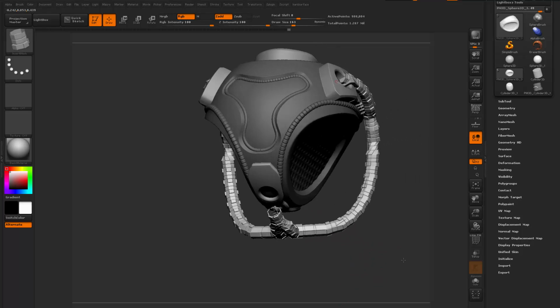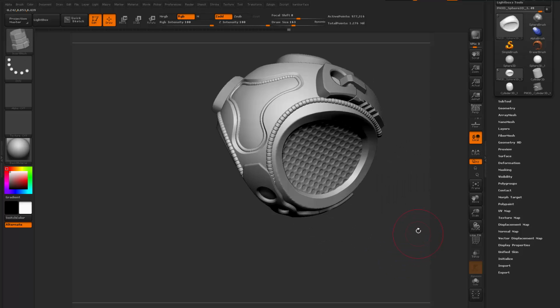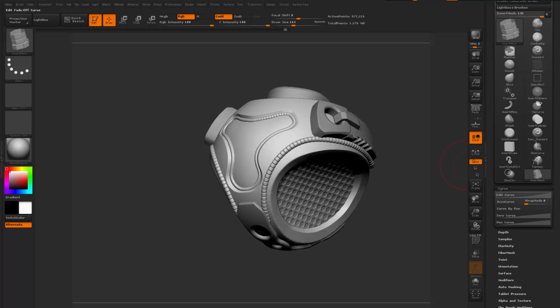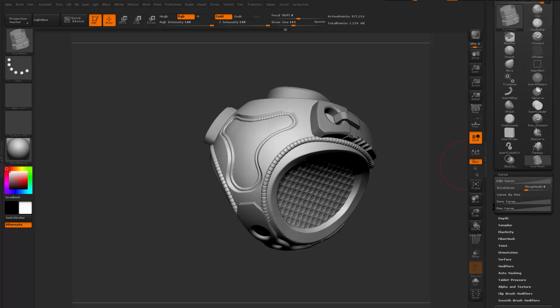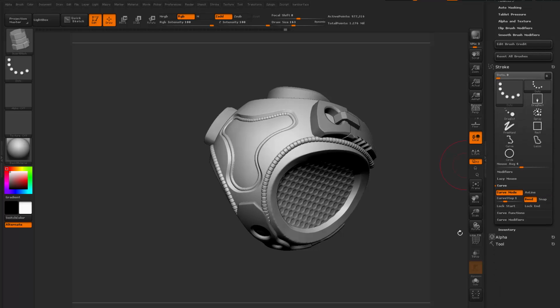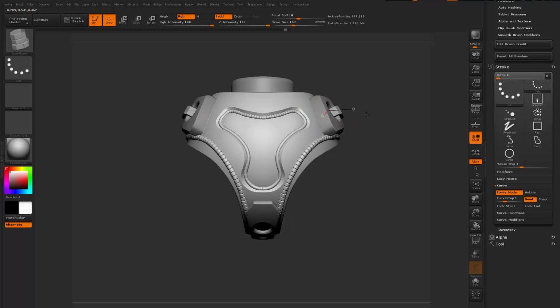Okay, now it will try to snap to objects. That's because underneath the stroke, the curve, there is the snap. Turn that off. That will prevent it from snapping, and then I can just draw it out like that. I don't want them to be meeting each other. We can turn off the symmetry for now.